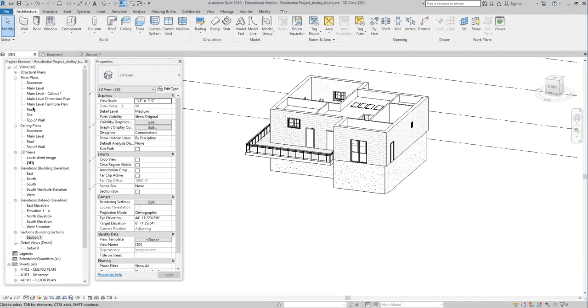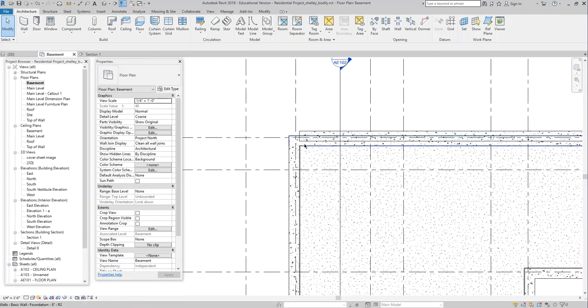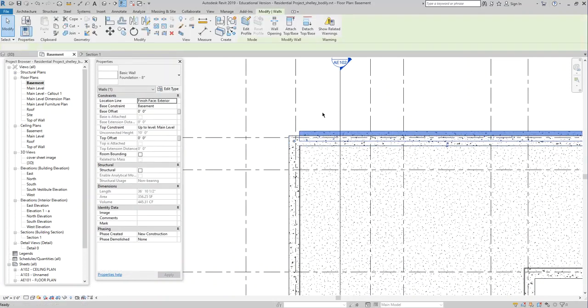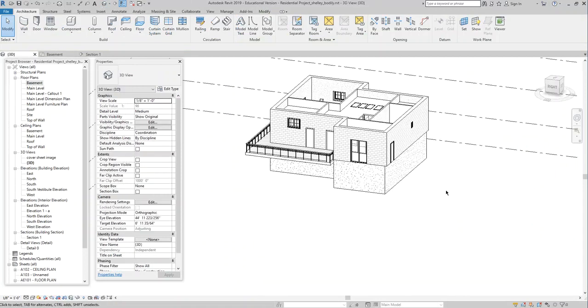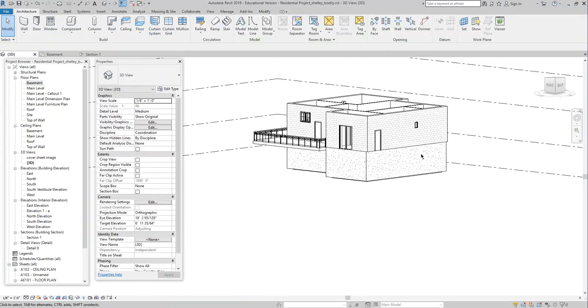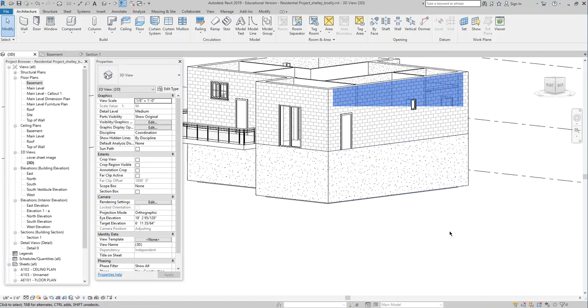Let's go to the basement level now. Oh. That's tricky. I must have clicked twice there when I generated this, because it looks like I have an extra foundation wall. So I just deleted that. Well, that solves the problem. AL, align, click, click, and there we go.